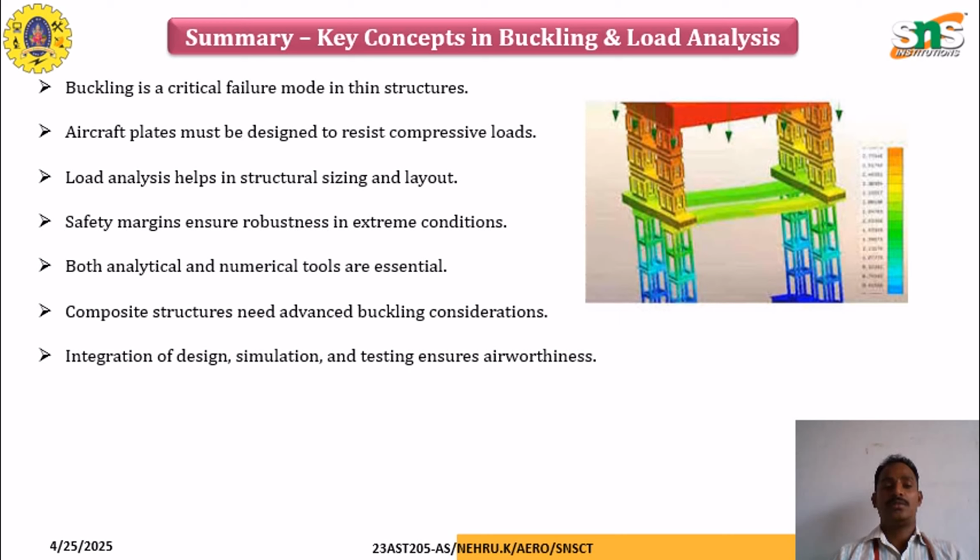In conclusion, on buckling and load analysis: buckling is a critical failure mode in thin structures. Aircraft panels must be designed to resist compressive load. Load analysis helps to understand the structural size and layout. Safety margin ensures robustness in extreme conditions. Both analytical and numerical tools are essential to understand the buckling behavior of structural components. Composite structures need advanced buckling consideration in advanced aircraft structures. Integration of design, simulation, and testing ensures airworthiness.